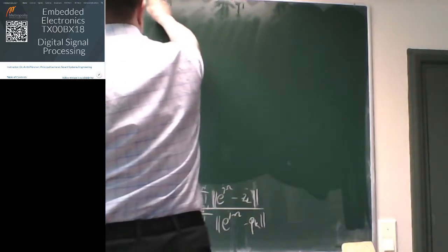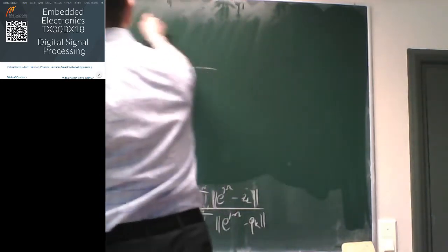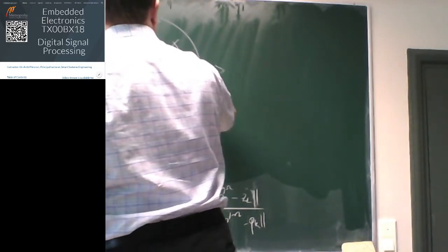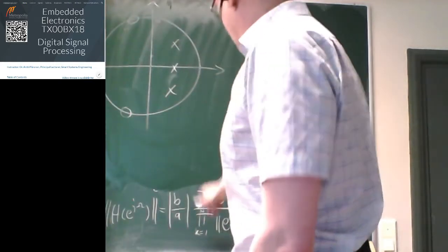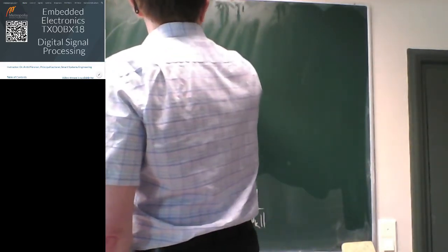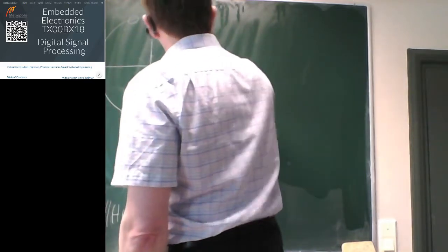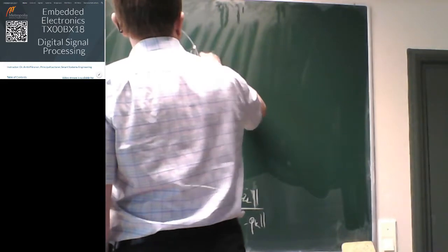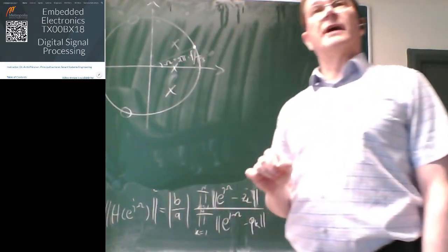Okay, on the zero-pole plot. If we have zeros, for example, at these kinds of locations, and then a few poles here, and then we have this e to the j omega somewhere in here. That's the location on the unit circle, where this angle here is omega, which is simply 2 pi times the current frequency divided by the sampling rate.